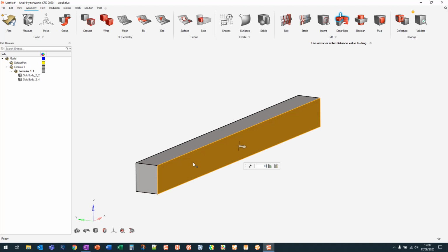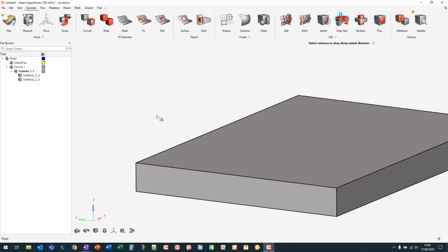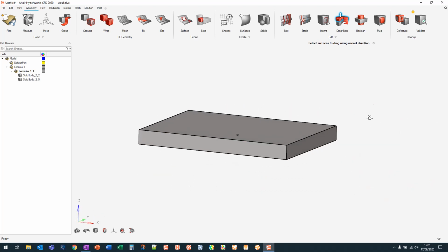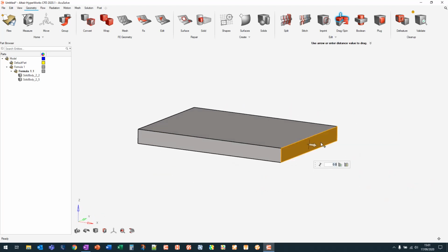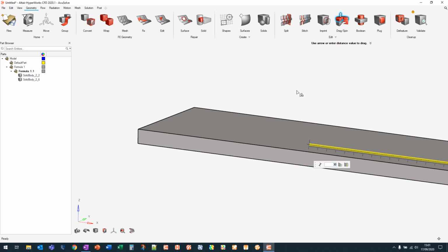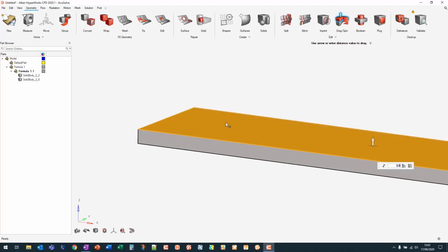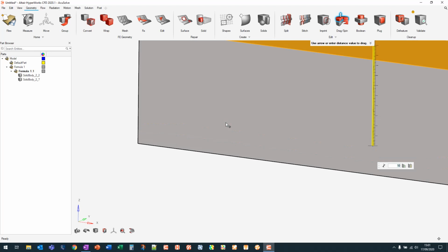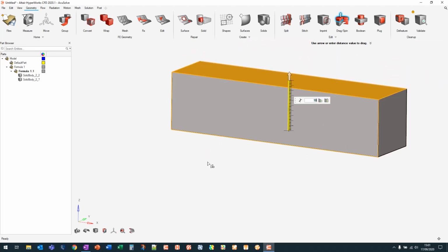So let's go 10 meters to the side of the car. Let's focus on the outlet region, so this will be maybe 30 meters behind the car, and then say 10 meters, repeat that to the top of the enclosure.